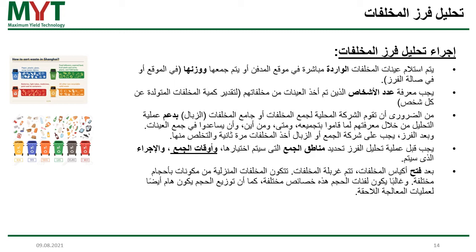And maybe also respect Ramadan, because sometimes Ramadan in waste management has to be seen as an extra season, because you have an extremely increased amount of food waste. So this has to be taken into account. And also sometimes rainy and not rainy seasons. So this has to be respected and a good procedure planned. You can conduct a waste sorting analysis, of course, only one time, which gives you a good overview. But sometimes these analyses are done, for example, in every season, or 4 times a year, just to see if there are big deviations in the numbers.